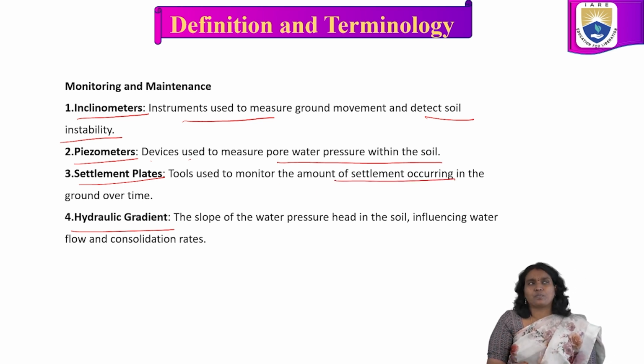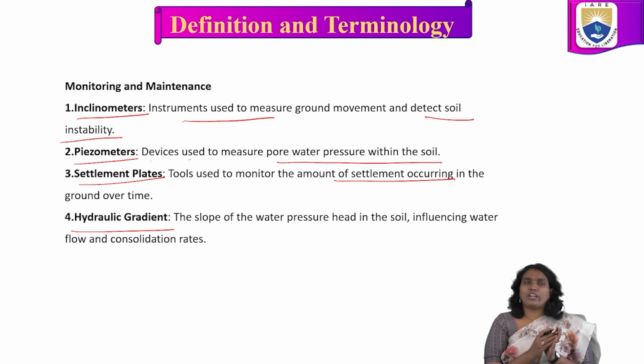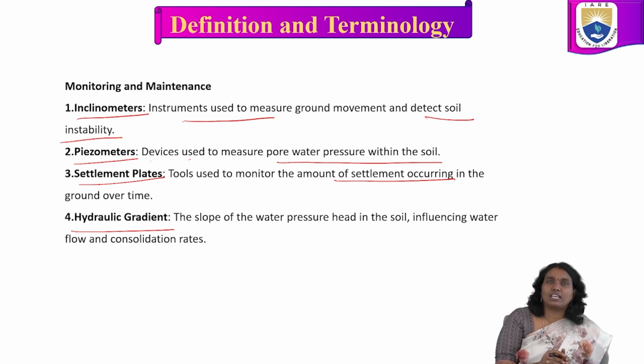Whenever we do monitoring before and after the construction, we use some tools to monitor after the construction work is done, to understand how much settlement is going to occur in the ground from time to time. So that is nothing but settlement plates.